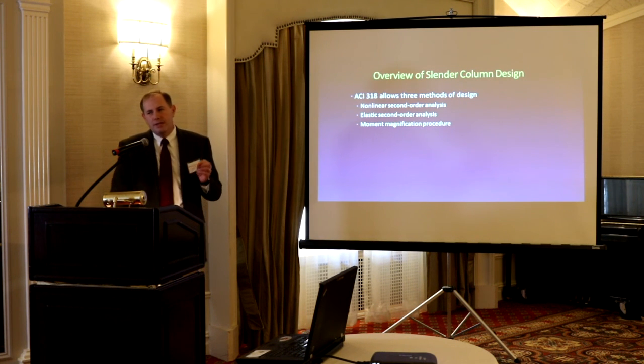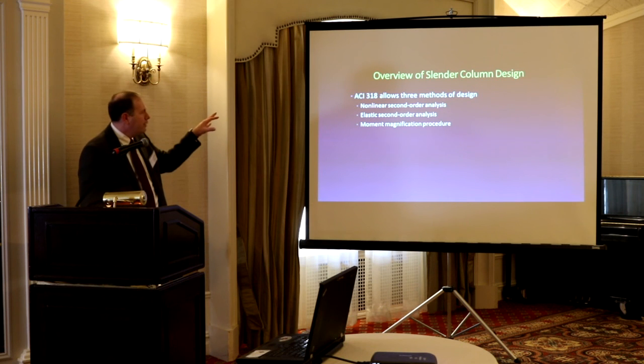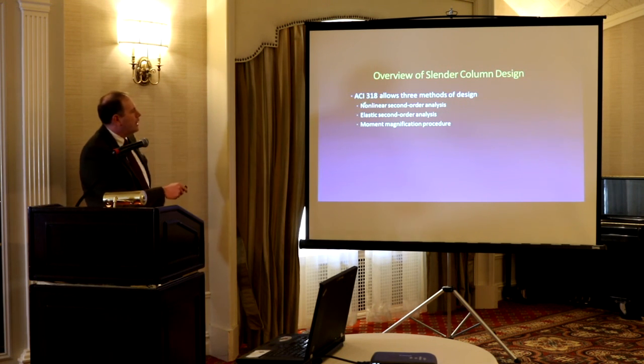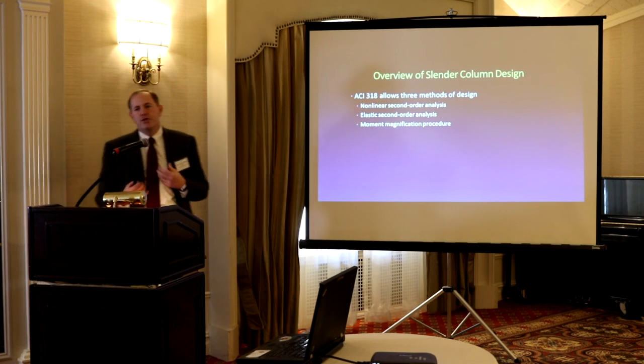Let me talk a little bit about design in ACI. 318 allows three different methods of design for these slender columns. There's nonlinear second order analysis. This is the most complex.